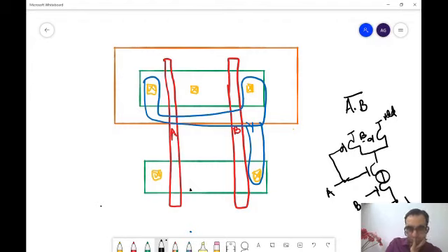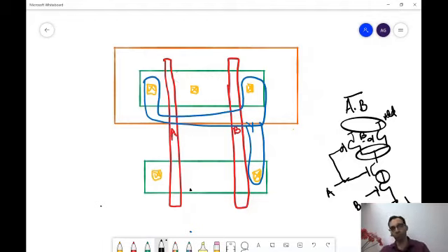Okay. Similarly, on the PMOS side, there are 2 PMOSs. And by virtue of this shared diffusion region, I am either making this connection or I am making this connection. Either of those two I am making. That is what my question is. Where would you use the shared diffusion? Shared diffusion should be VDD or shared diffusion should be output? That is what my question to you is. Output. Shared diffusion should be output. Why? Because we get our output from the middle of the PMOS and the NMOS.